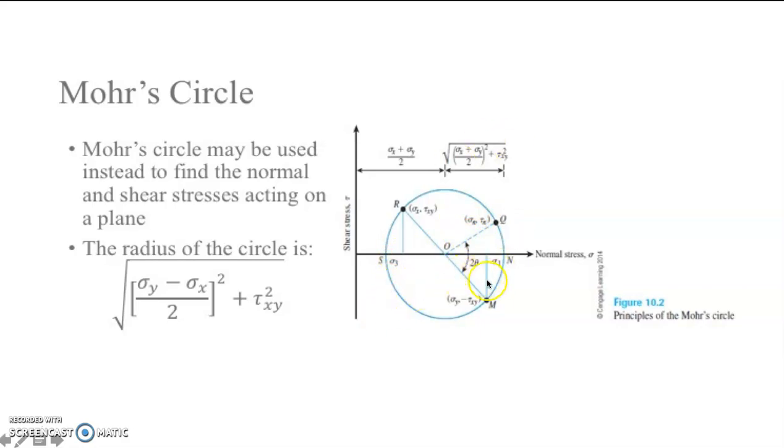So basically, we plot our major principal stress and our minor principal stress. From here, this is our minor principal stress, which is denoted by sigma sub 3, and our major principal stress is sigma sub 1. You simply have to identify each value, then plot on our figure, and then to have a Mohr circle, having the value of sigma sub 1 and sigma sub 3, you get its center, use a compass so that you can have a perfect circle here.